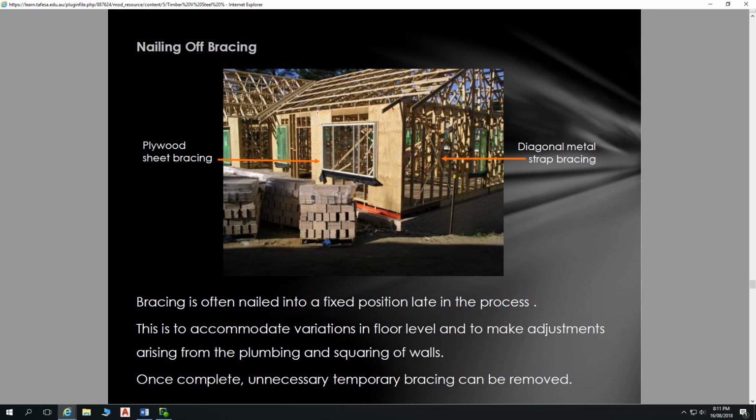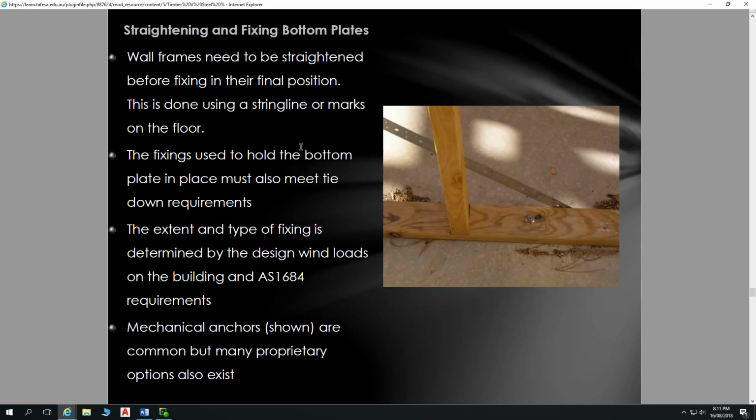So it's not just about going, oh yeah, we'll use sheet bracing for that 900mm section there, and then the rest can be standard framing. No, you have to carry that bracing all the way through, because otherwise it just involves packing it out, and you've got to pack it out with plywood anyhow. So as designers, you have to think about that. If you're specifying sheet bracing for a frame and cladding building, you've got to continue that line all the way through with the wall frame.